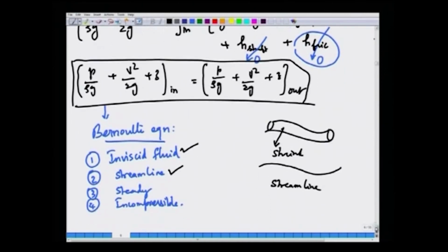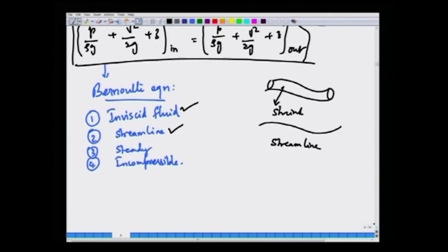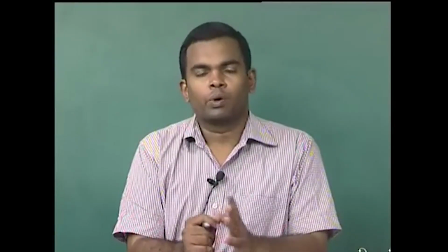Whereas, the energy balance that we wrote is generally applicable to any control volume, okay. And as long as you can supply the problem with the information about what the viscous losses are, you can completely solve it, okay. And it is applicable to any flow of viscous liquid into any equipment like a pump or a piping network and so on. As long as we know what the losses are, we can certainly solve that most general energy balance equation, the integral energy balance equation, okay.